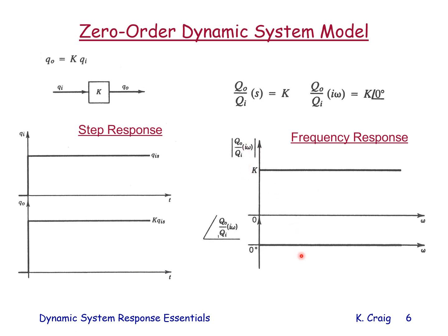If we plot that versus frequency, we see that for a zero-order system, it's constant. There is no frequency dependence. It's just K. And the phase angle between the input and output sine waves is 0 degrees. There is no phase lag. If you input a sine wave at any frequency into a zero-order model, you get a sine wave out. Same frequency, no phase shift, and the amplitude is just K, which is the amplitude ratio of the output over the input.